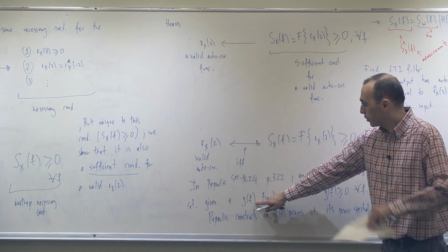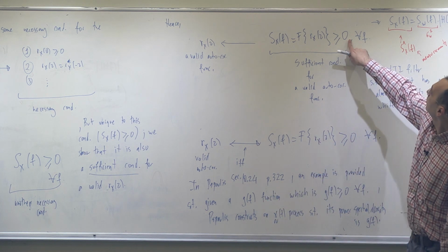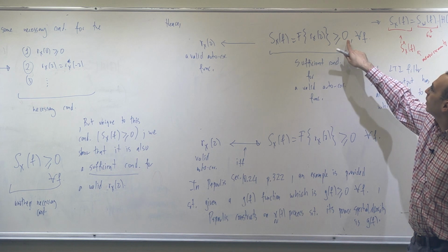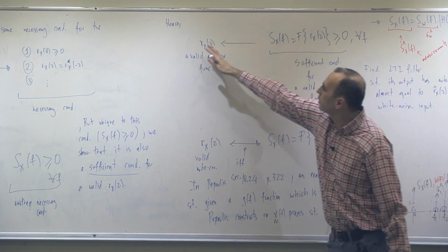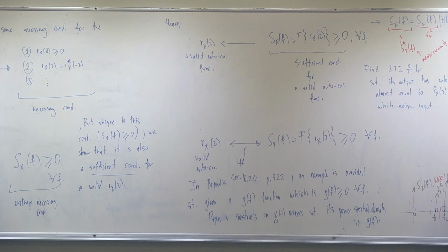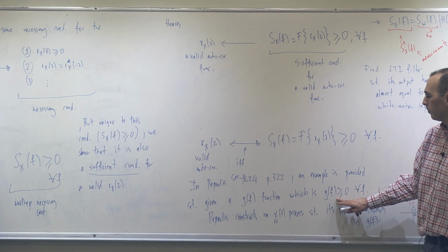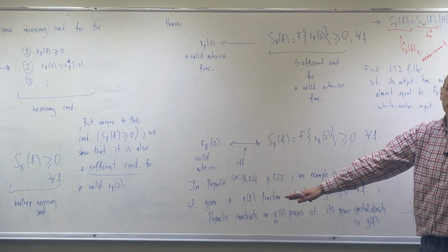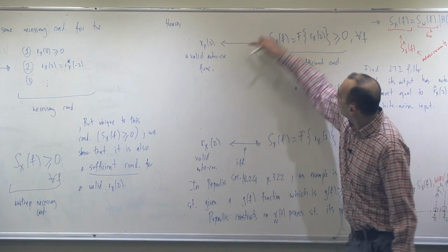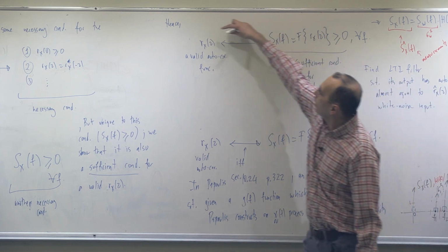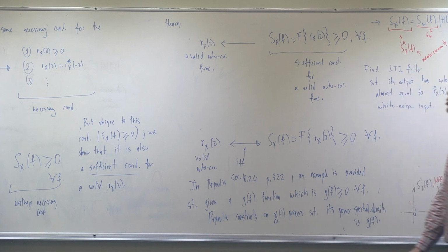Okay. So this time Papoulis does the following. If I have a function which is always non-negative, then Papoulis treats that function as a power spectral density function and constructs a random process x of t such that it is indeed the power spectral density. So for any G of f, I can always construct a process. And this is what I want actually, because given this is satisfied, I can construct the process with power spectral density exactly that.